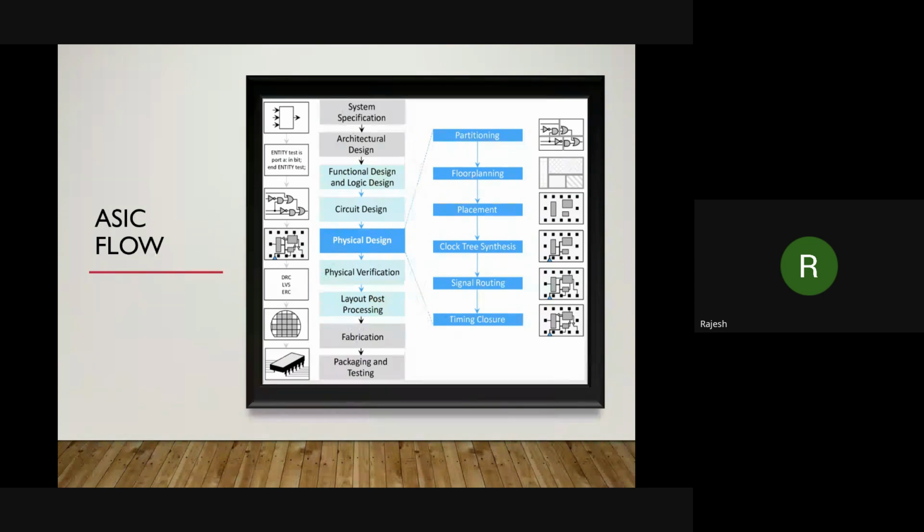Now the main thing, the physical design. From physical design, everything we will call back end. Whatever the front end people did required more simulation and testing, which is a logical thing. They cannot see any physical objects in the design; they just write a code and test that code. So everything they test is in terms of logic. But when it comes to physical design, the real layout is created, the real chip is created with some height and width and everything. Whatever the physical designer designs, that chip will be manufactured directly. However you place and design your circuit, the circuit will be manufactured directly like that. That is why from physical design to everything below it is called back end.